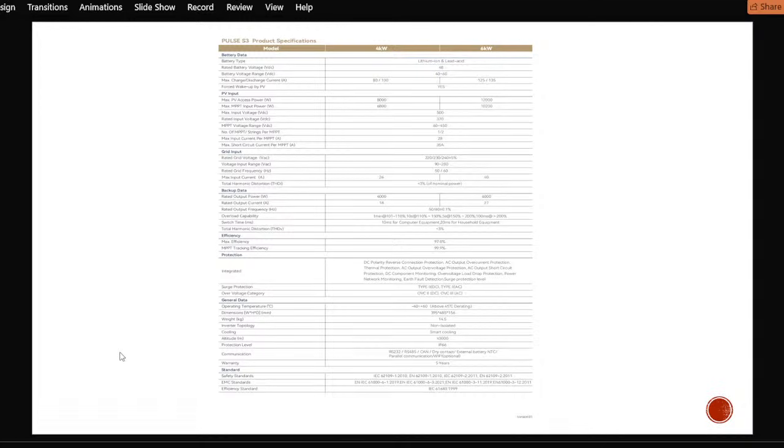Now, this is the Pulse ELS2 11 kilowatts. Unlike the 6 kilowatts, which is IP66, this is IP21. It is an indoor inverter, right? It has built-in dual MPPT for tracking, and each of them takes around 27 amps. So it gives you the capability and leniency to max out on the PV that you can input on the system. Each of them supports 27 amps, like I said.